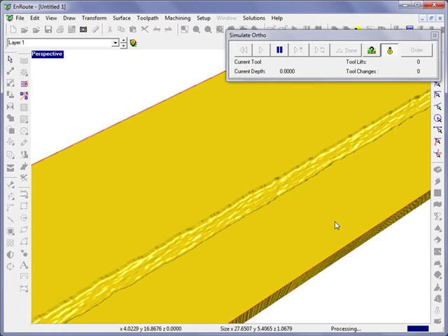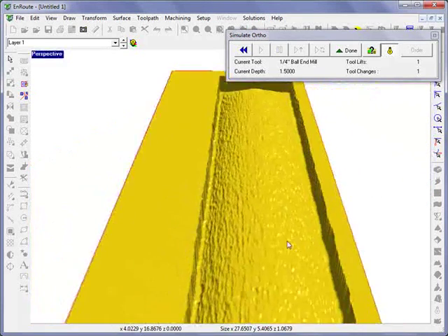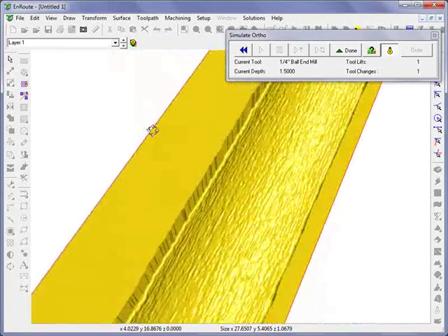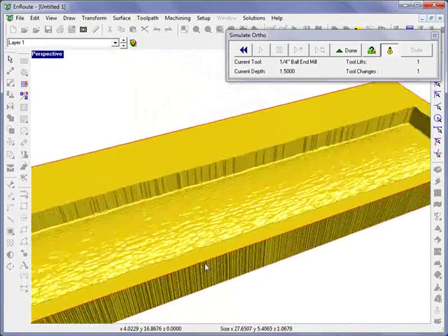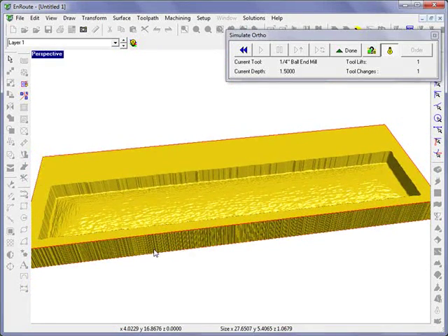I didn't have to apply a texture or create a surface with a texture or use rapid texture even. My regular toolpath, once I applied it and distorted it, would introduce a texture to this part. So this way it almost looks kind of like some bark. So these are two ways you might use the toolpath distortion to introduce texture or to remove some type of tooling marks introduced during the toolpathing process.